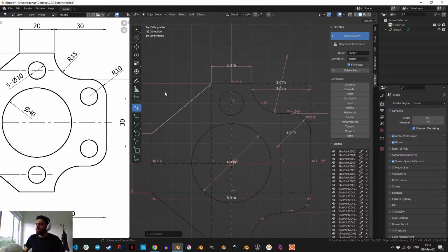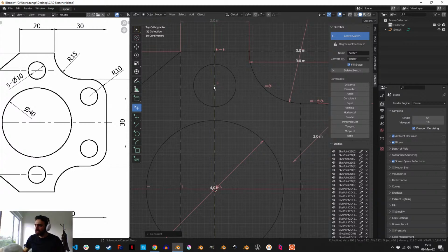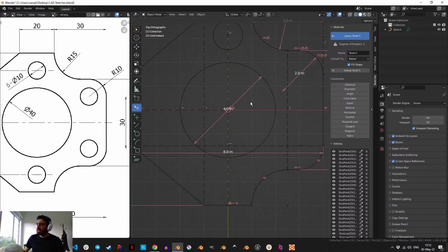Yep, that's good. This makes it so that the circle actually slides over this line, which is perfect. And let's just add another one. Hopefully, if I create the second circle with this element highlighted, the coincident constraint is already added, as you see. The trick is not deleting it, because deleting a constraint is too easy right now.